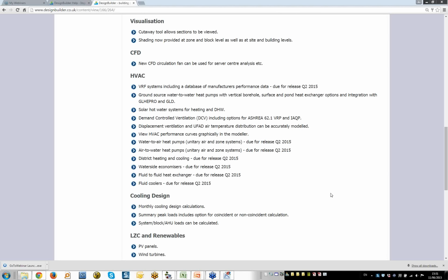Can building and component blocks be differentiated in the GBXML import? Yes, well, they'll be differentiated in the Revit or whichever BIM program that you're using. And yes, they'll come into DesignBuilder differentiated. So spaces, surfaces, etc. will define a building block, and shading surfaces will define component blocks.